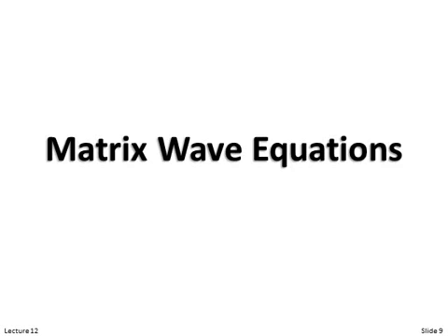So that's the full story with the periodic boundary conditions, and now you should have all the information that you will need to go ahead and write a function to build those matrix derivative operators. You'll hand it the size of the grid, and in the case of one of these pseudo-periodic or Floquet boundary conditions, you're also going to need to give that function the k-inc, your incident wave vector, and the period of the device, so that it can incorporate those periodic boundary conditions correctly.